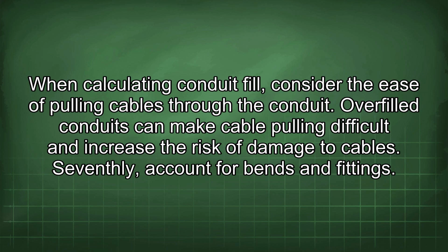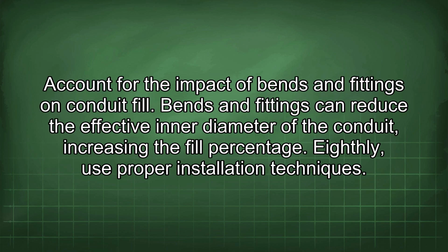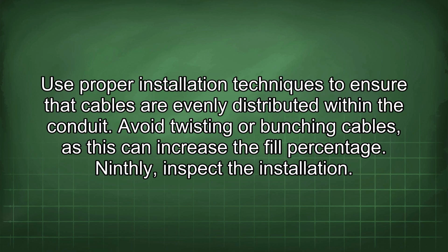Seventhly, account for bends and fittings. Account for the impact of bends and fittings on conduit fill. Bends and fittings can reduce the effective inner diameter of the conduit, increasing the fill percentage. Eighthly, use proper installation techniques. Use proper installation techniques to ensure that cables are evenly distributed within the conduit. Avoid twisting or bunching cables, as this can increase the fill percentage.